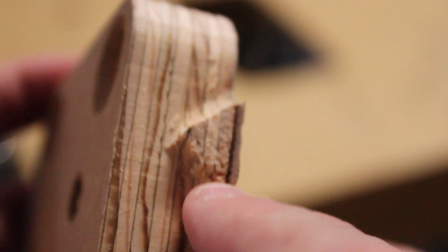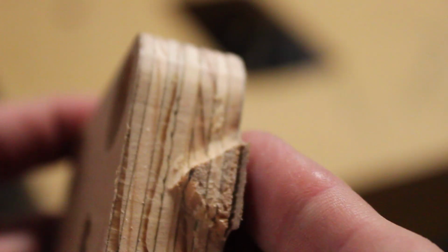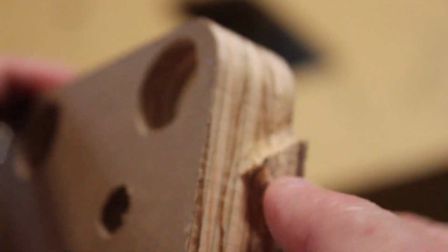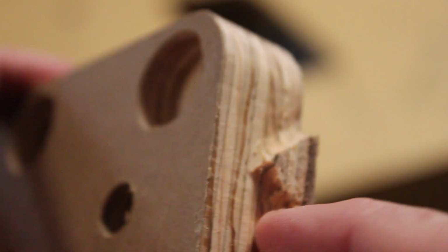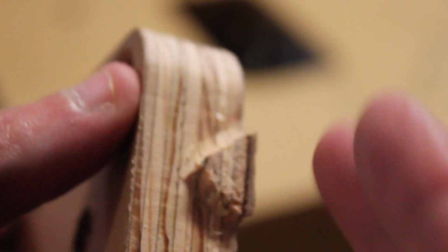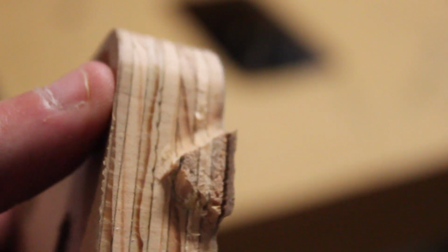The holding tabs will leave you with these triangular or square pieces, depending on the configuration of your holding tabs. You'll be left with this stock on the edges, and you can see the height of the tab, and then you can see that there's a nice smooth section just above the tab, so I can take that and use that as a bearing guide. So let me show you my method of getting rid of these tabs quite quickly and easily.